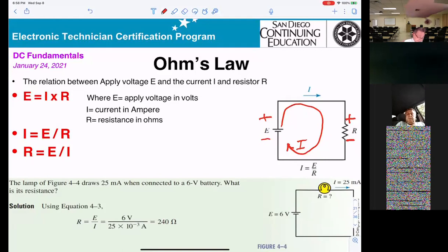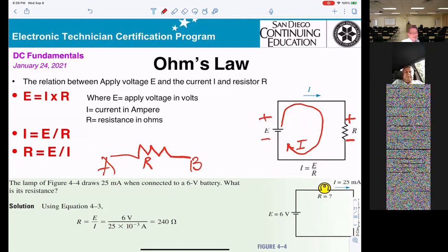So that's why when you're in the field, they draw the resistor with ends A and B. They will ask you which side is positive, A or B. Now, how can you answer that? I just draw that resistor from A to B, and I ask you, tell me which side of that resistor will be positive and negative. A is positive, B is negative. You don't know until they put a source on it.